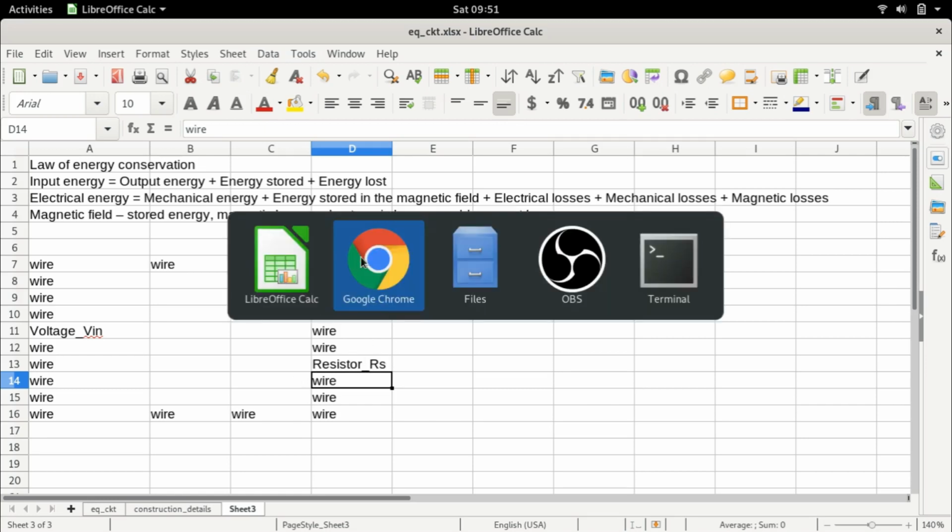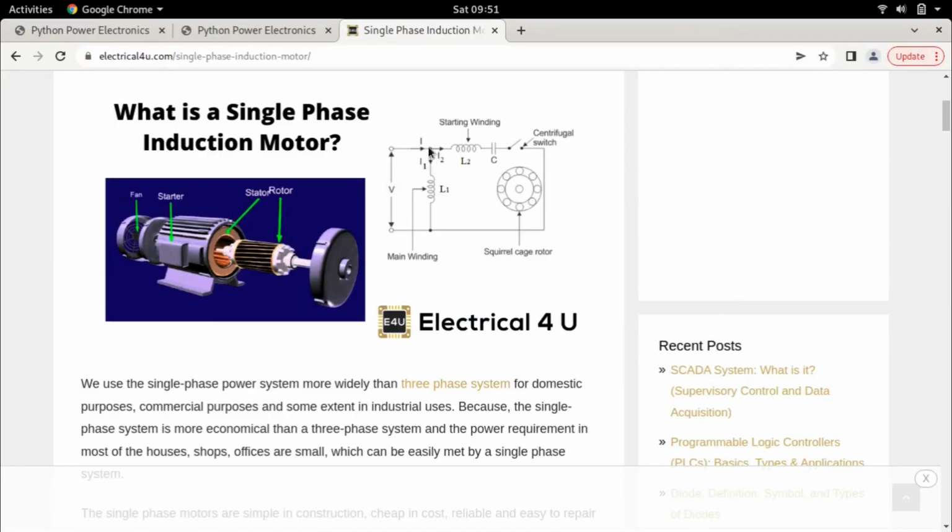So if you come back here and have a look, all we are saying is we are going to cut out this entire part of the circuit. So just forget that everything right of this does not exist. All we have is this voltage feeding this inductor. Now they haven't shown a resistor, but quite obviously a winding will have a resistance, and all we are saying is we are putting a certain parasitic resistance in series.